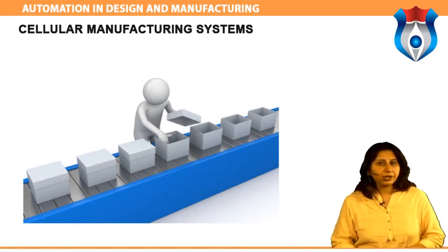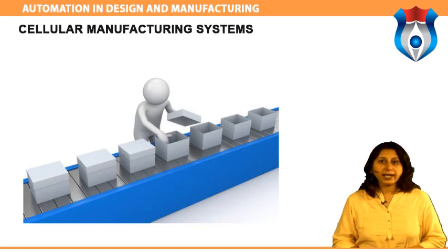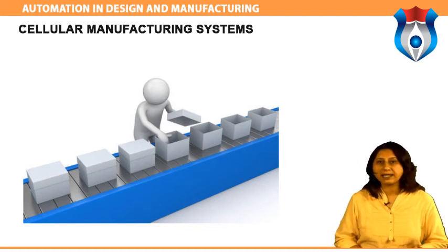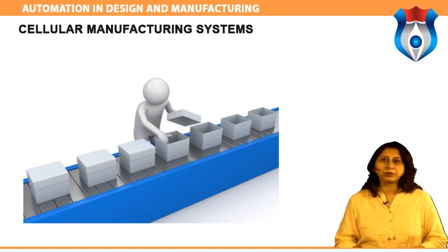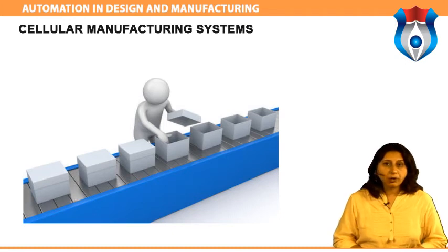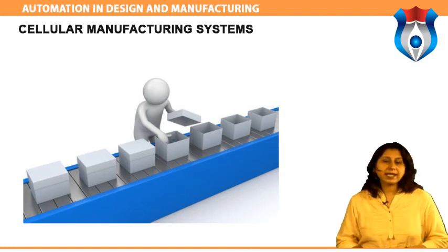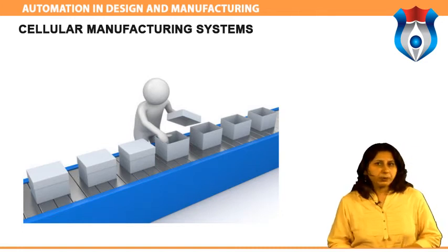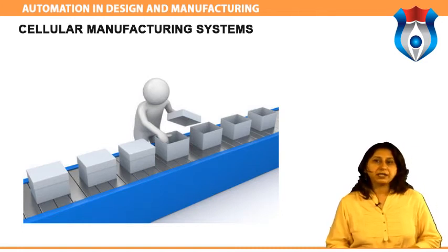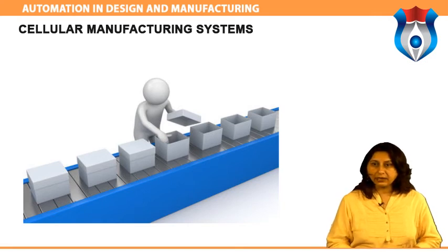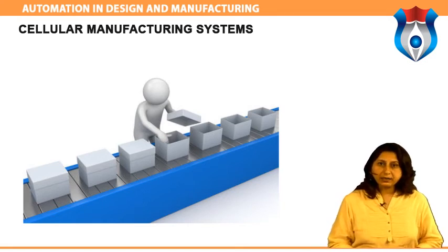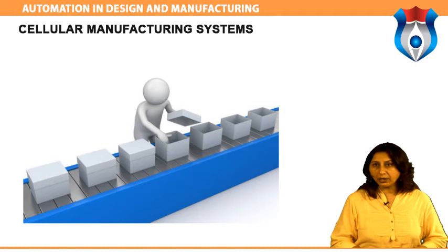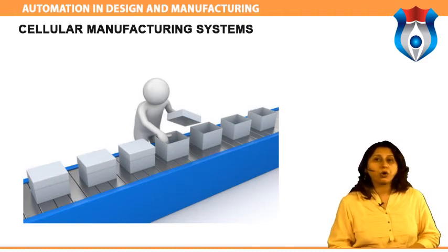To make the cellular design work, an organization must often replace large, high-volume production machines with small, flexible, right-sized machines to fit well in the cell. Equipment often must be modified to stop and signal when a cycle is complete or when problems occur using a technique called autonomation.